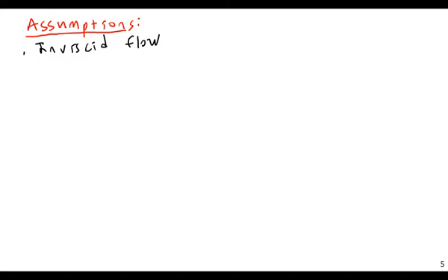So there are a few very niche cases where you could get perfectly inviscid flow, but in basically any kind of material or fluid you'll be dealing with, unless you're designing MRIs or something, there is typically no case of truly inviscid flow. But even though I admit that this is completely impossible, it isn't actually that bad. For most of the fluids where we use Bernoulli's equation, this assumption is not perfectly fine, but it's good enough.